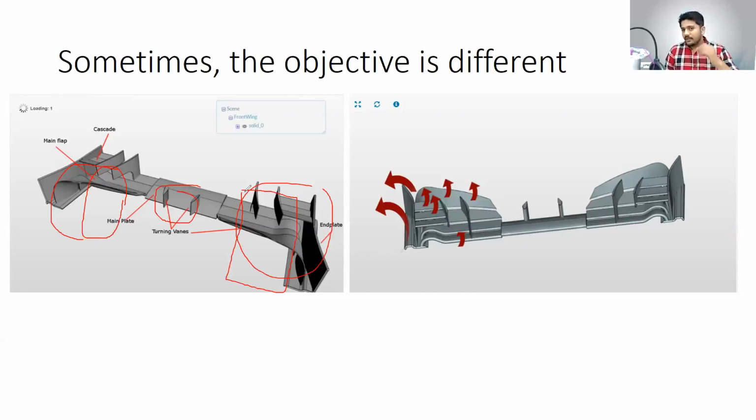But remember, the reason why you're still trying to do aerodynamic simulations is not because CFD will give you the results accurately. As I will talk about in a later slide, the very term computational fluid dynamics means you're approximating your solution. So you will have some errors. The only reason simulation is being used, again, I cannot repeat myself enough, is it's a very cheap tool, right? You can actually run several iterations. For example, in this case, I can try out different end plate designs, and I can run a lot of simulations and figure out, okay, this end plate is much better than the other end plate. Not in terms of absolute values, but in terms of trend. And that is where CFD shines.